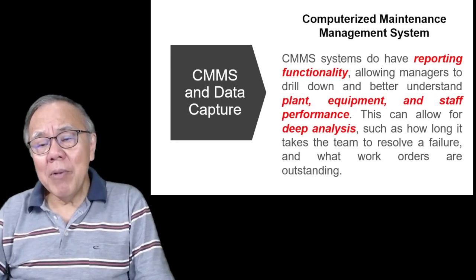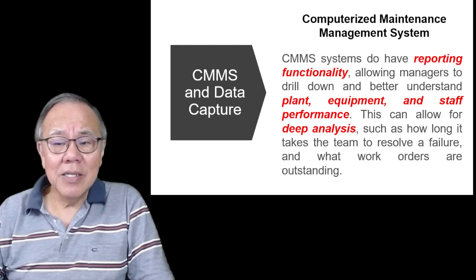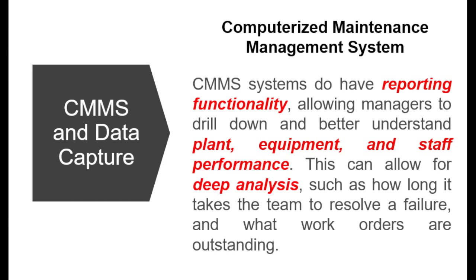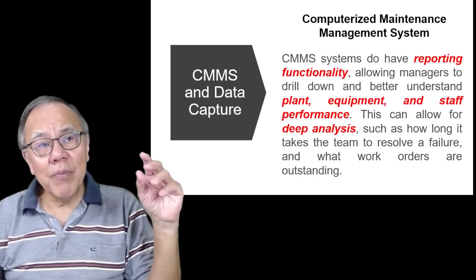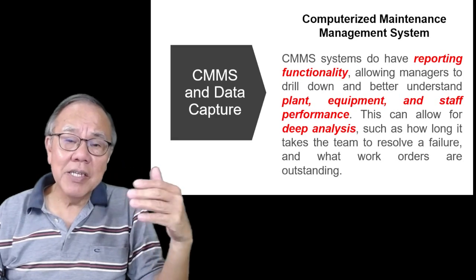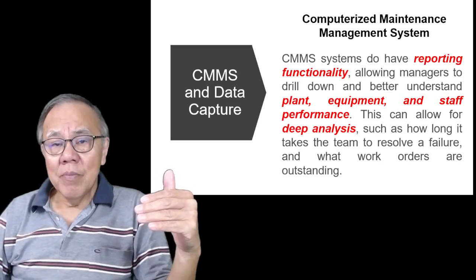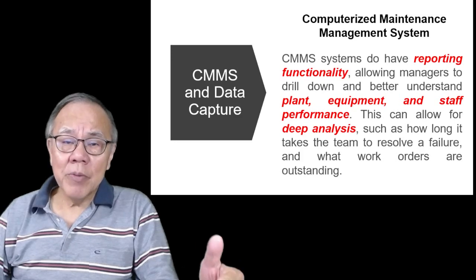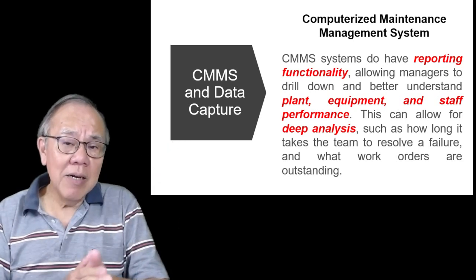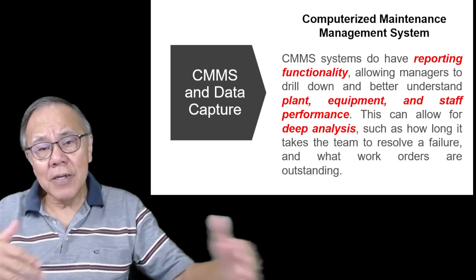So CMMS also has reporting functionality, allowing managers to drill down and better understand plant, equipment, and staff performance. This can allow for deep analysis. In other words, if you have a breakdown, for example, and you categorize it and say this time is a motor problem, the next time is a belt problem, the next time is a gear problem, so if you collect all this data on a regular basis